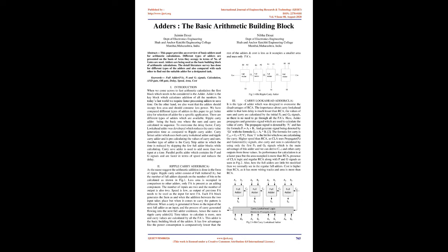Time taken to calculate is more, as sum and carry values are calculated by all the FAs. This adder is the basic building block of the adders. It has a few advantages: the power consumption is comparatively lower than the rest of the adders, and cost is less as it occupies a smaller area and uses only FAs.